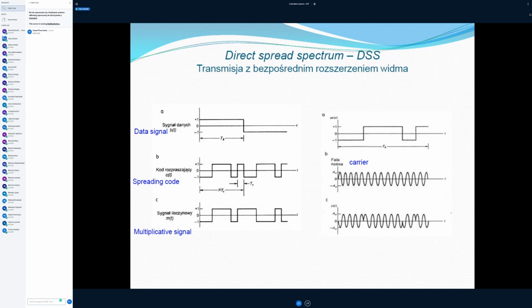That's why our frequency modulation is not now having only one carrier, but it has a lot of carriers. For example, in this case, it would have 7 different carriers, and of course, the signal would be in various bands related to those 7 carriers.